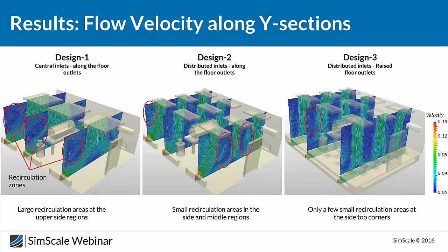That's why it's very important not to have these recirculation zones. Otherwise, the contamination gets localized at part of the room, and through diffusion, slowly, gradually, again enters the rest of the domain. But it never successfully and efficiently leaves the interior of the clean room.